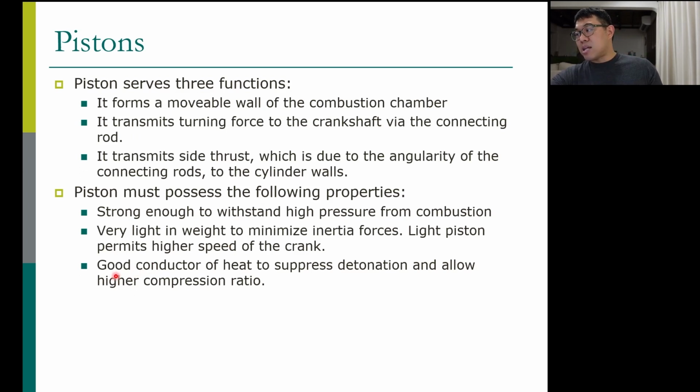Then the piston has to be a good conductor of heat, because we want to remove heat from the combustion chamber. If the top of the piston is still hot, then in the next cycle, when the fuel and air go in, they can burn because the piston is too hot. The piston has high temperature and can ignite the air and fuel.